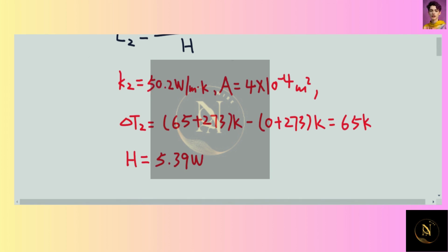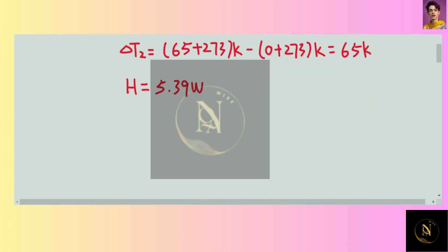And if we do some calculation here, we find the change in temperature is 65 Kelvin. And from our last question, we know the heat conduction rate is 5.39 watts, because these two parts share the same heat conduction rate since they are connected to each other. Okay, so we can just use the heat conduction rate from the last question. So therefore, we can determine L2,